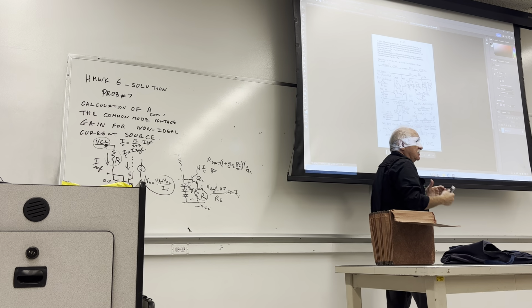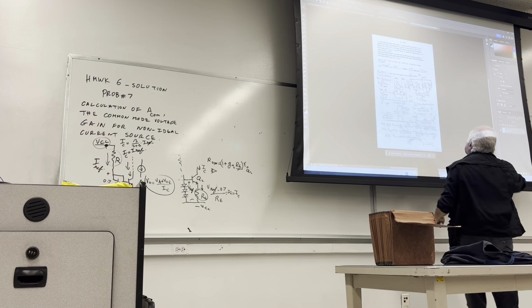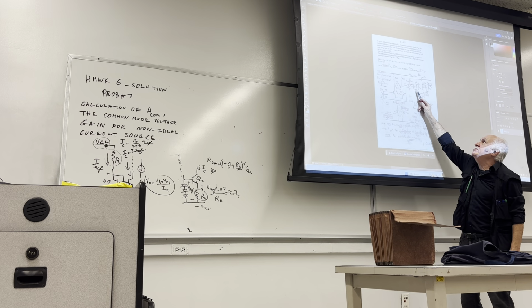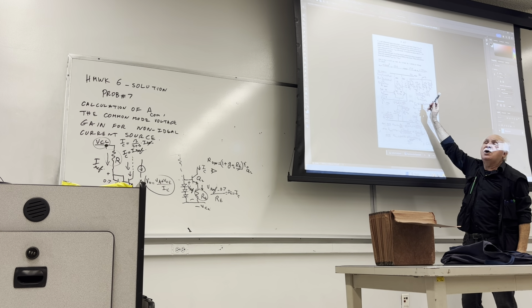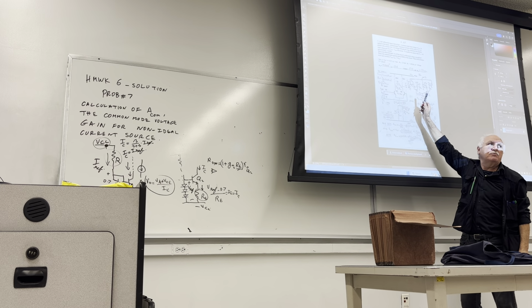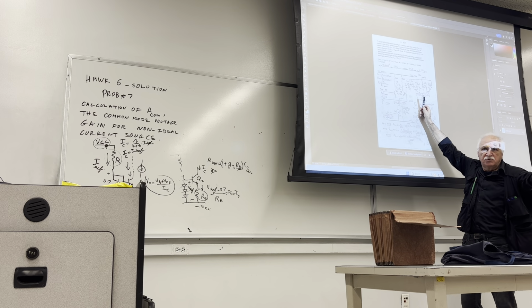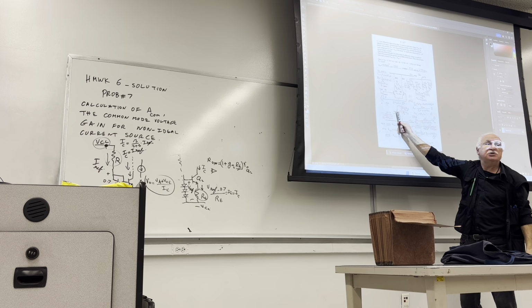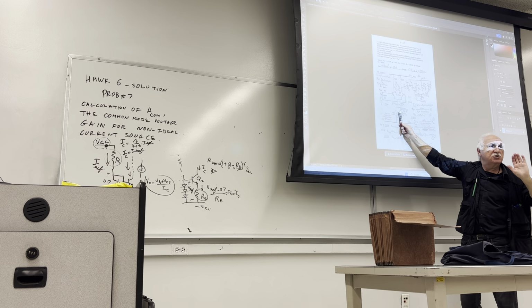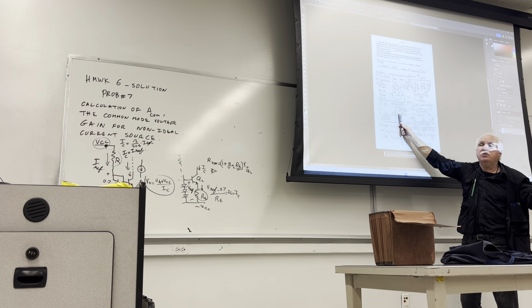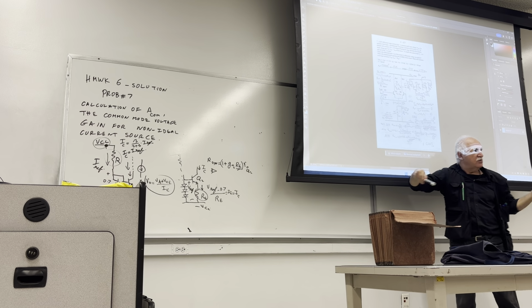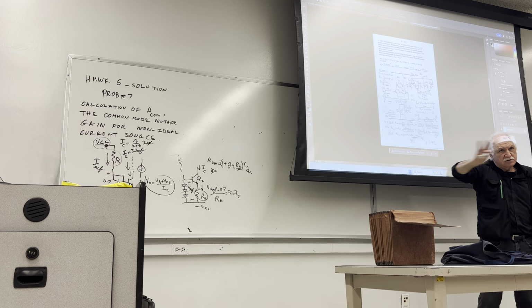So how do we analyze to get to the formula? This is the model for both transistors, draw them. Put all constant values to 0. Remember the signals. You put DC values to 0. Please, this is a DC value, constant value. When you zero it, it disappears from the screen. So when currents are zeroed, they're out of the circuit.